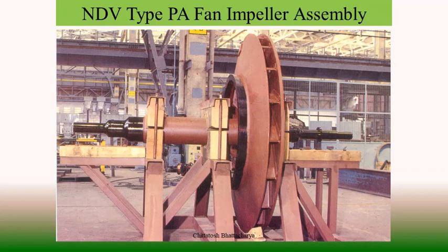For ID fan, the arrangement is double suction type mostly, and radial fans. As there is double inlet and radial discharge, you will find that inlet guide vanes are placed at both side suctions, or rather than inlet guide vanes, there are suction dampers, and on the discharge side also we are having dampers, and these dampers are placed in such a way that there is no Coriolis forces or flow separation that can occur.